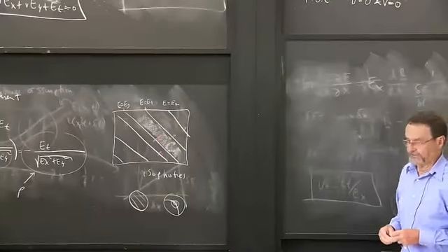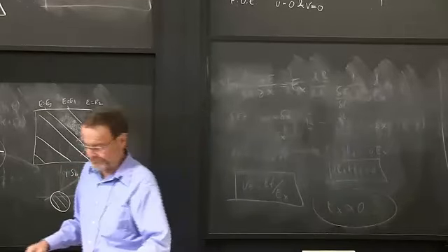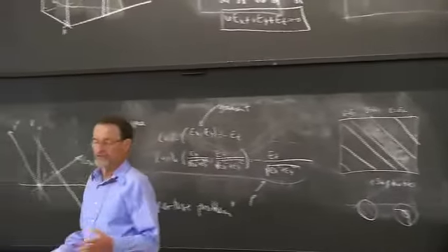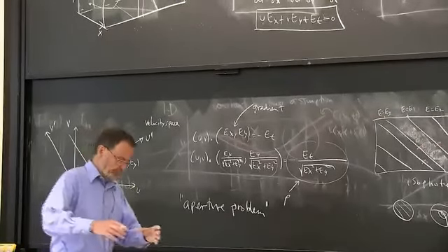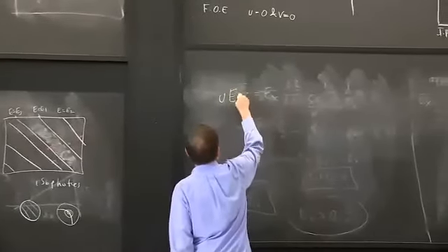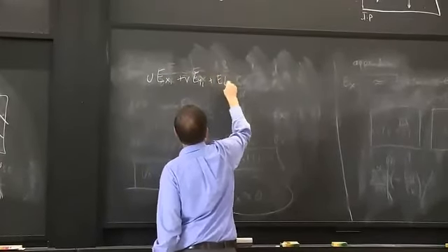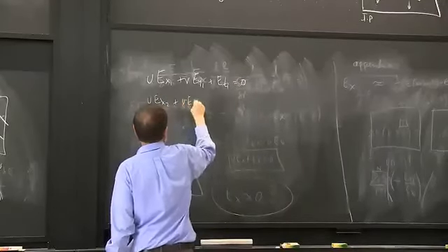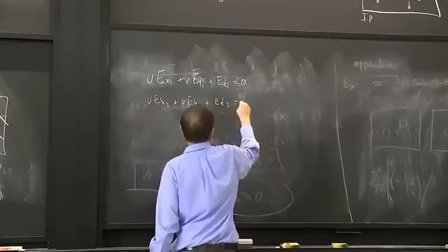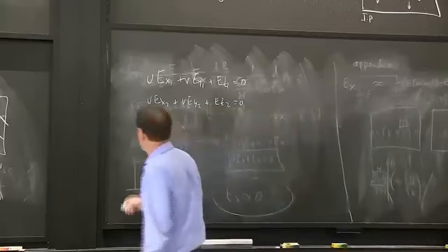Now let's suppose that we have the optical mouse problem where the whole image is moving as one. You're over a flat surface at a constant distance from the lens and to a very high degree of approximation, the image is just moving as one. So we don't just have one pixel. We can do the same thing at 2 pixels. Okay, that's at pixel 1. And that's at pixel 2. And our job is to recover u and v.